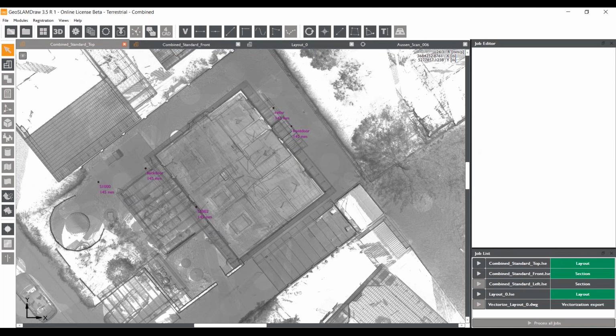Next question for you, Ivona. For corridor mapping, how long should the corridor be? I think the same practice applies whether it's Horizon or the Revo: you need to make some loops. If it's a corridor of 50 meters long, that's fine with Horizon, because you can easily walk 100 meters straight and then make some loops around the features. With the Revo or the Revo RT system, you should not walk more than 30 meters in a straight line and then make some local loops around.